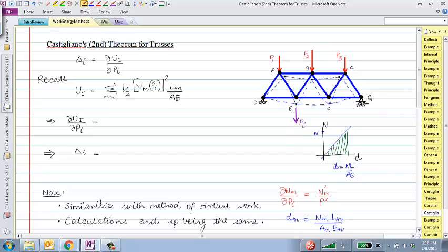Right? That's the energy stored in the structure. So we have real loads P1, P2, P3. We have an additional load which we will change from Pi to dPi, and we'll try to find the derivatives of that. So if we change that load dPi, then we are just taking the derivative of this expression, and we can do that by adopting the chain rule.